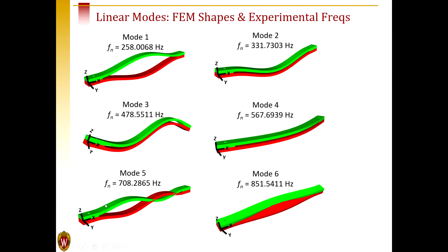As background, these are the main modes that were measured. So we have various different kinds of motion. The beams are kind of opening up and clapping in this mode. In the second mode, they're kind of bending in unison. And you can imagine these are going to stress the joints differently. This one wants to open and close, so the axial stiffness in the bolt along the z direction might be really important there.